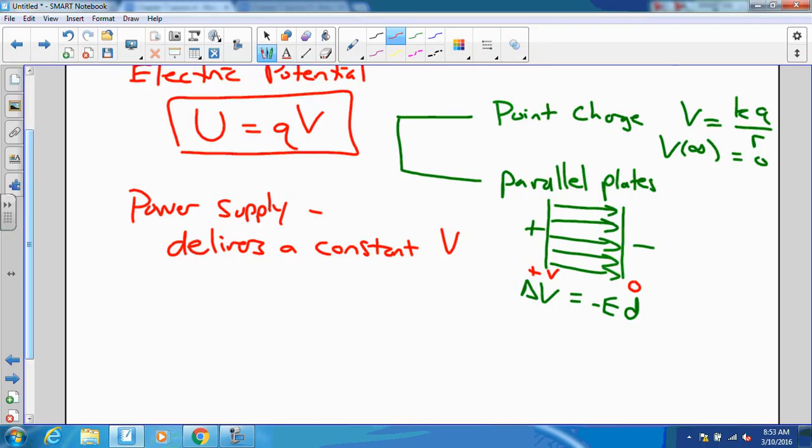You can go ahead and hold that and read it for us. And again, I'm going to simply put the negative probe right here and ground it like that, so I don't have to worry about it. And then I'm going to take and touch the positive probe to whatever I want to read. What am I getting?